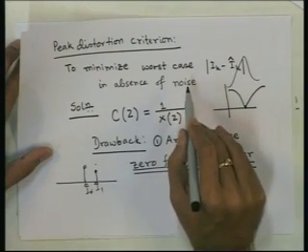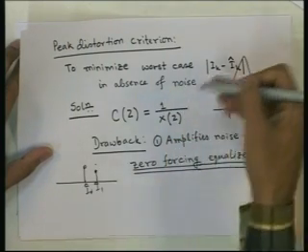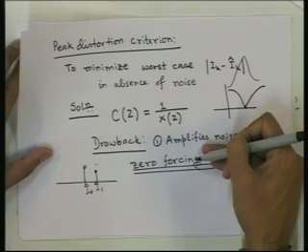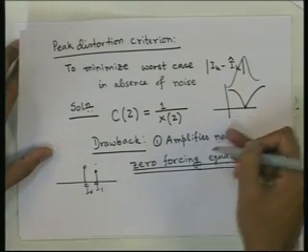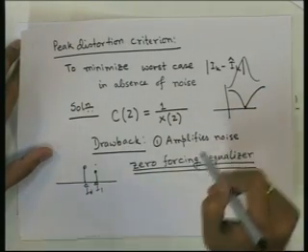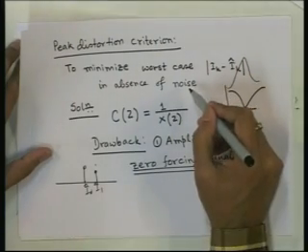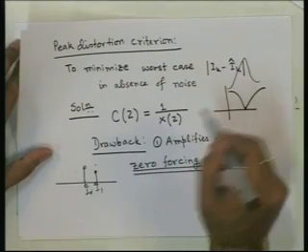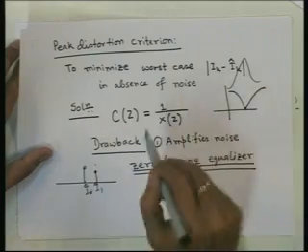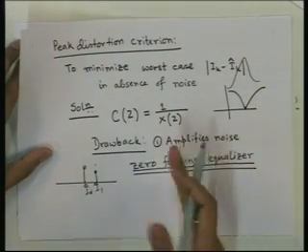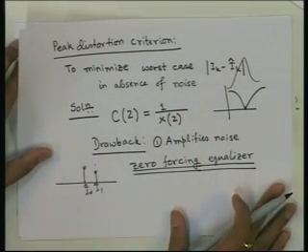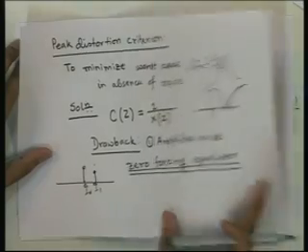So, we did not consider noise at all, and that ultimately resulted in a solution which amplifies noise too much in some bands. So, if we want to avoid the problem, we actually need to consider noise as well as interference together and design an optimum system. So, what criterion should we take for that?